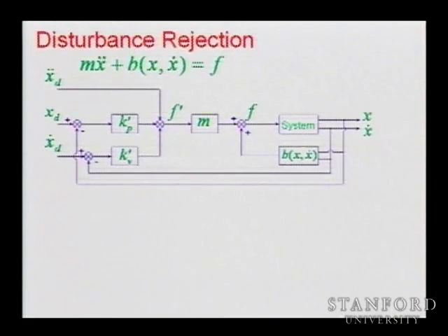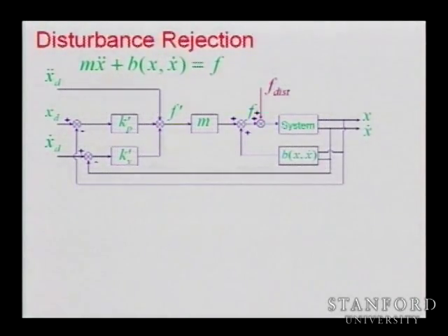So when we were running the simulation, already we saw that a small external force will disturb the system. There are a lot of forces coming from the errors in dynamics, errors in the gravity estimates, nonlinear forces coming from the gears and friction that will affect this behavior. And as we start introducing disturbances in the system, we are going to see that these gains that we set are going to play a very important role in disturbance rejection. So let's add a little bit of disturbance here.